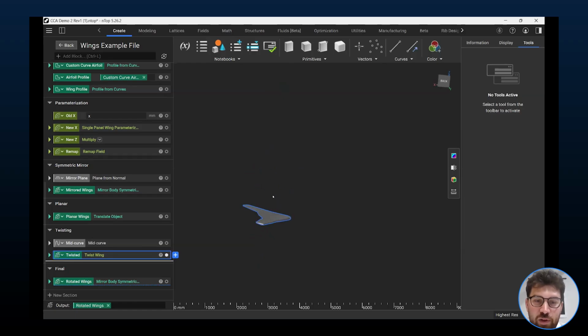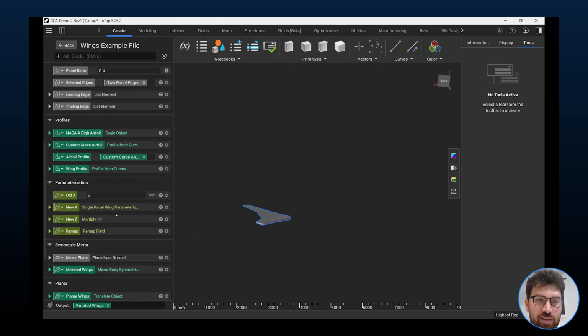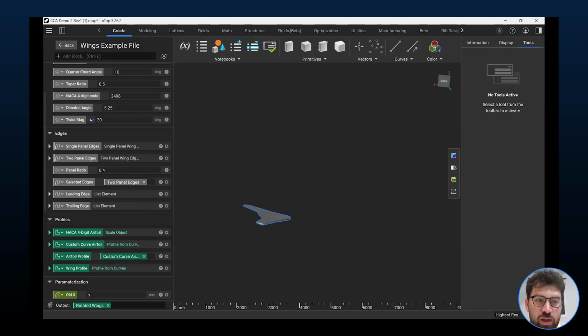So it might be a little bit difficult to see in this case, but we've actually done about a 20-degree twist. And if I actually drag this slider using the GPU modeling capabilities of nTop, we can actually see this twist update live. Now, if I let this go and do a more precise render, I can actually then see that 78, about 79-degree twist along our body.